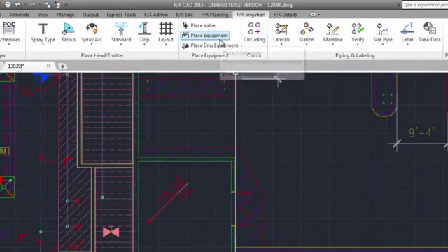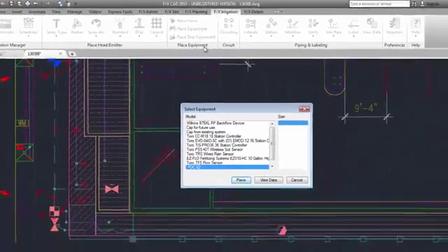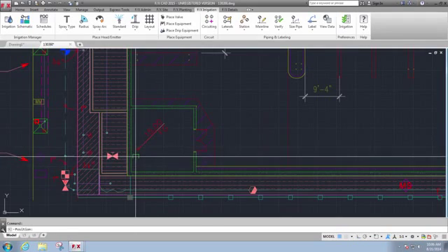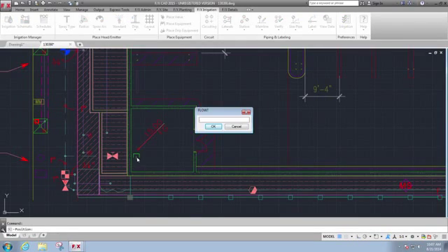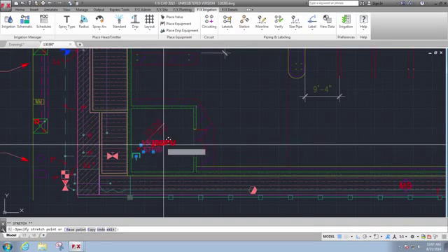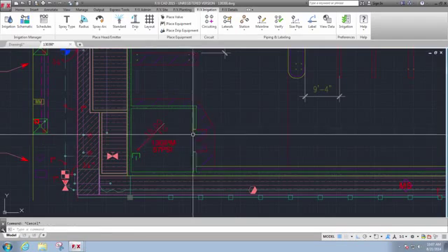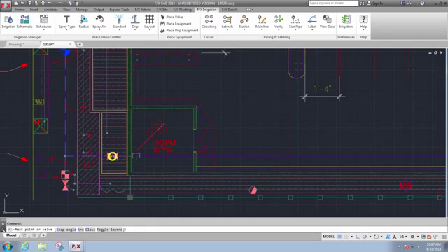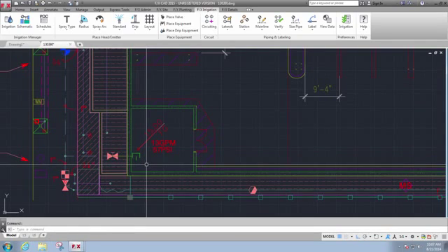Once this is added to the Irrigation Manager, add it to the plan with the Place Equipment button, and when prompted, input the demands for the cap at the second story. Again, that is 57 PSI and 13 gallons per minute for my example. Make sure to connect the new cap to the rest of the system, or a shutoff valve in this example.